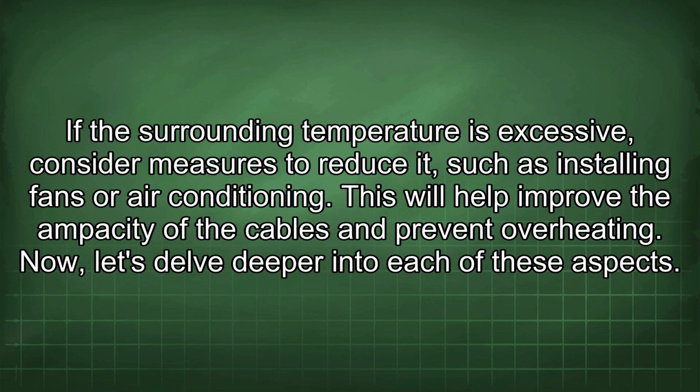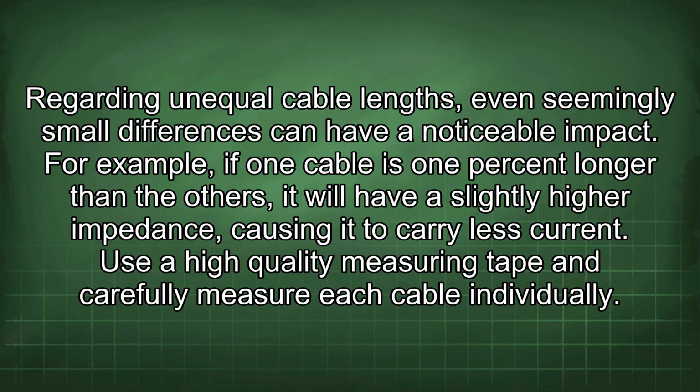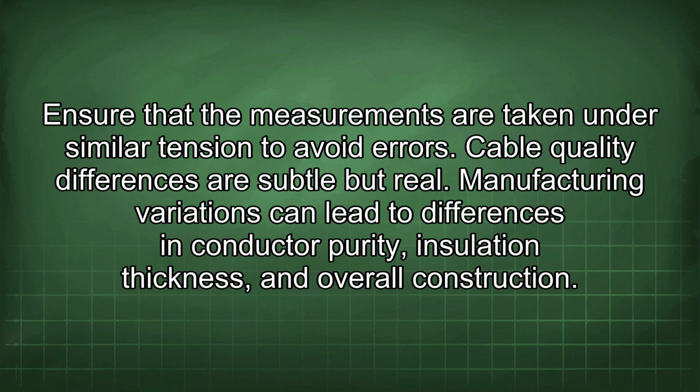Now let's delve deeper into each of these aspects. Regarding unequal cable lengths, even seemingly small differences can have a noticeable impact. For example, if one cable is 1% longer than the others, it will have a slightly higher impedance, causing it to carry less current. Use a high-quality measuring tape and carefully measure each cable individually. Ensure that the measurements are taken under similar tension to avoid errors.